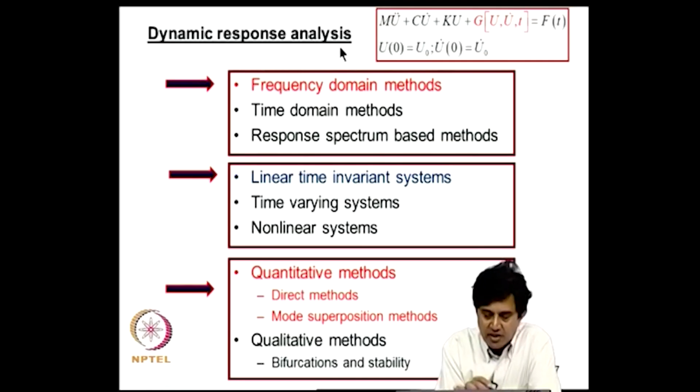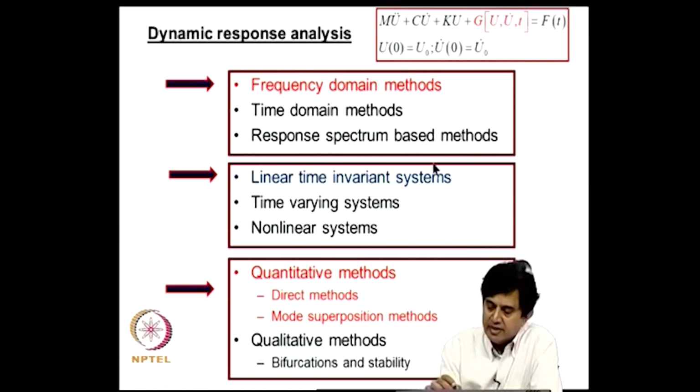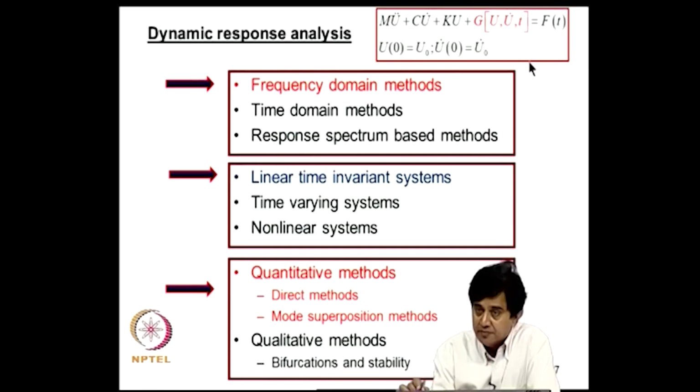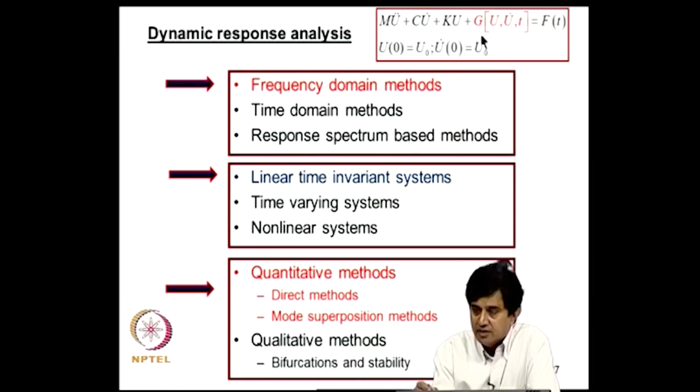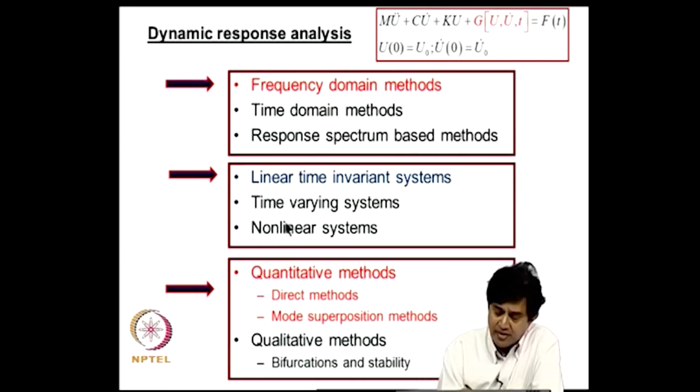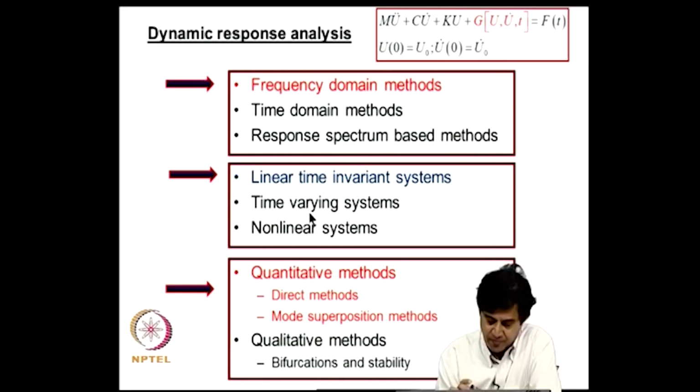Now, the response analysis procedure can also be viewed from the point of view of whether the system is linear, time invariant, that is M, C, K are independent of time, or the system could be time varying where either M, C, K or this nonlinearity function could be time dependent, or the system could be nonlinear where g, this function g, is non-zero. So, the methods of analysis also depend on this classification of the systems.